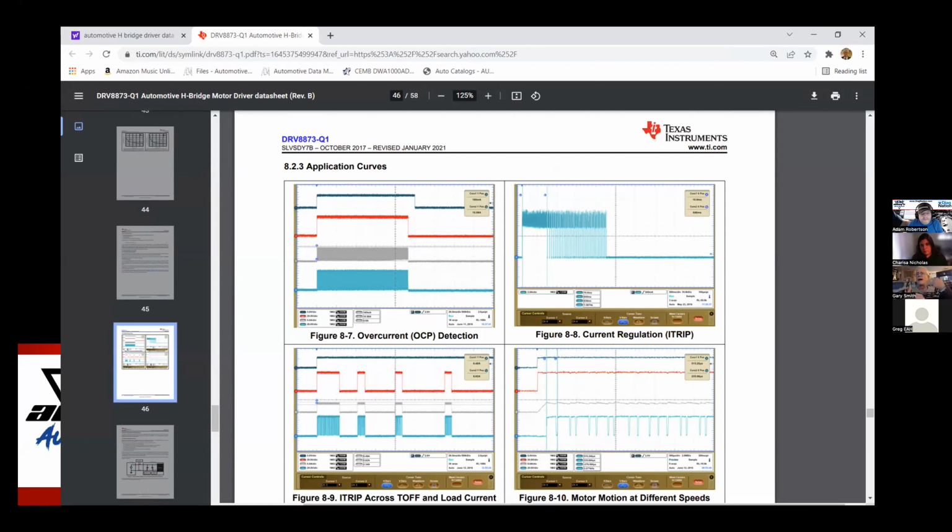What I'm pointing you guys to is a diagnostic direction here to understand what's going on. In most of these scope waveforms, they'll be tied on the data sheet to one of the protection lockouts. Here, you can see this is overcurrent protection. Look what it does to the driver. It shuts it off. But what's going to happen here, and I wish I'd have taken this picture one step down, is this is going to set about a trip, a motor trip and protection strategy, if you will.